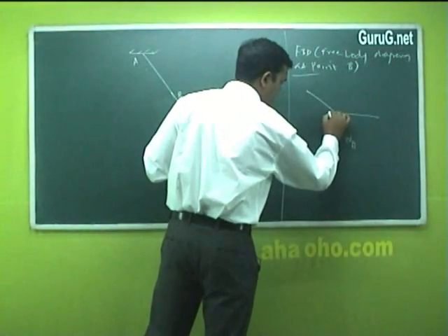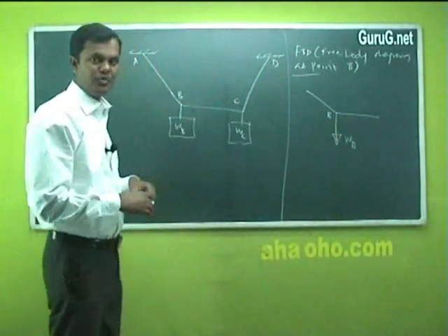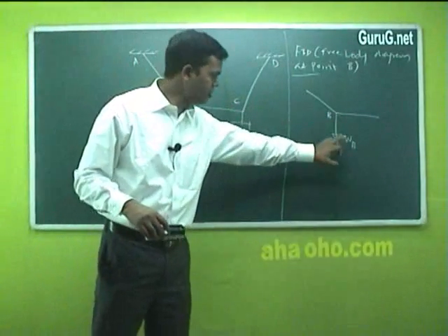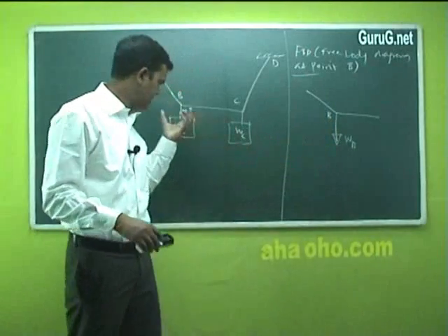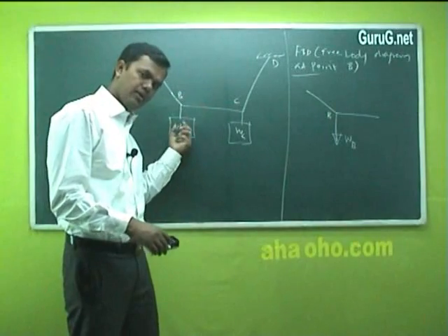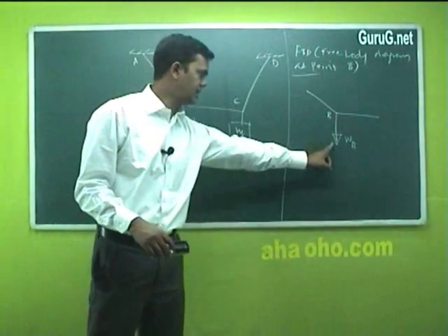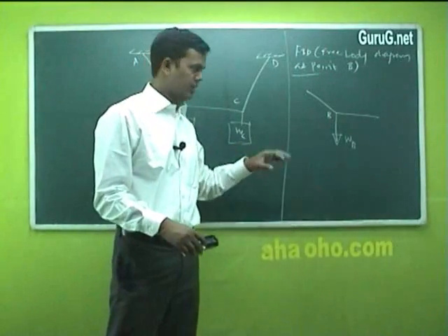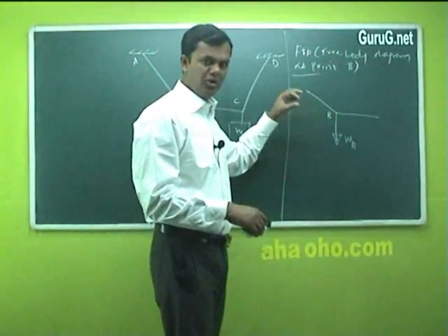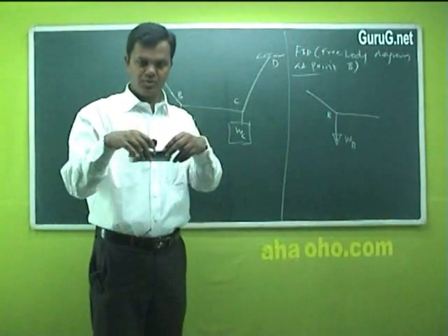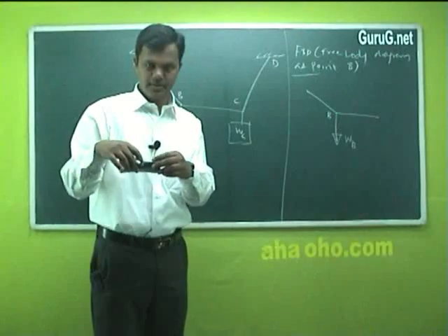So this becomes your point B. Now I have to decide how I should indicate the arrow mark. This arrow mark I have drawn downward because the self weight of this body will always pull down. So I am indicating weight as a downward force. Okay. Now to keep the body in equilibrium condition means stable. It should not become imbalanced, or it should not oscillate.